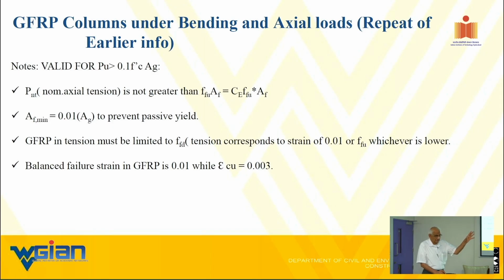You remember all that? Where is that coming from? Because when a crack forms, God forbid it won't, but even if it does, that crack is going to cut through the two contiguous ties, whereas you don't have that problem with a spiral. When if there were a crack.